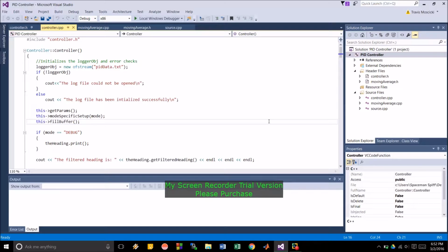You can either not turn the anti-windup feature on until you get within a certain margin, let's say plus or minus 3% from your set point. Or you can turn it off after you get within that plus or minus 3%.